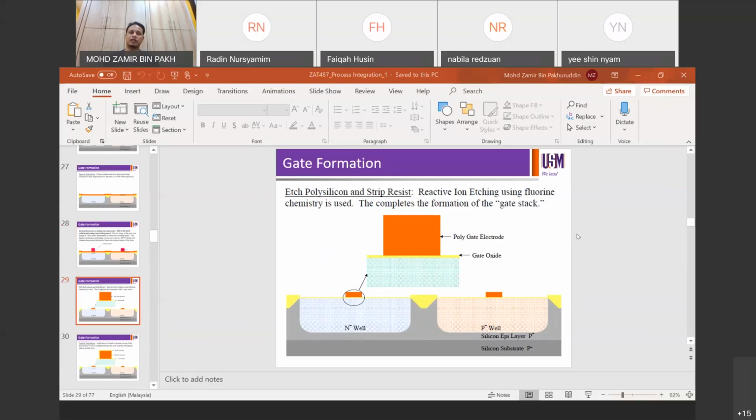But when it comes to the definition of technology node, we have a couple of definitions around this. But it's not on the metal, it's on the polysilicon layer, right? Because that forms the gate of the device. So remember, when you talk about the transistor, you have to go back to the gate, source, drain. And in this particular case, you already have your gate made of polysilicon, and that's where you define the size.